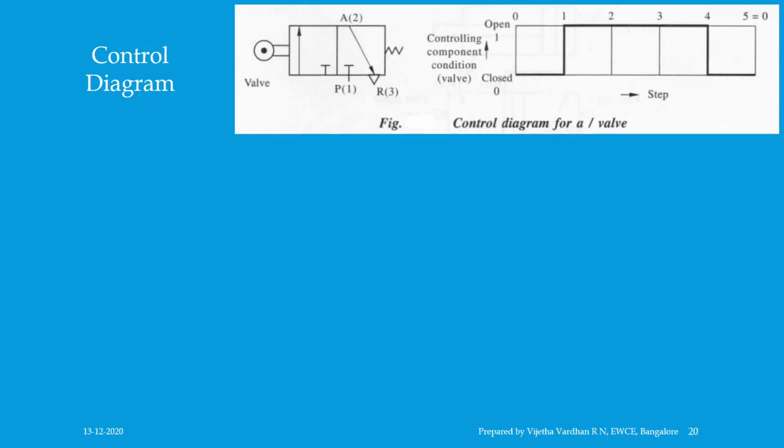And the recommended procedure for control diagrams and how to write that. The control diagram should, if possible, be drawn in conjunction with the motion diagram, and steps or time should be entered horizontally, and height or separation are optional but should be selected to ensure clarity. The combination of motion and control diagrams is called the function diagram.